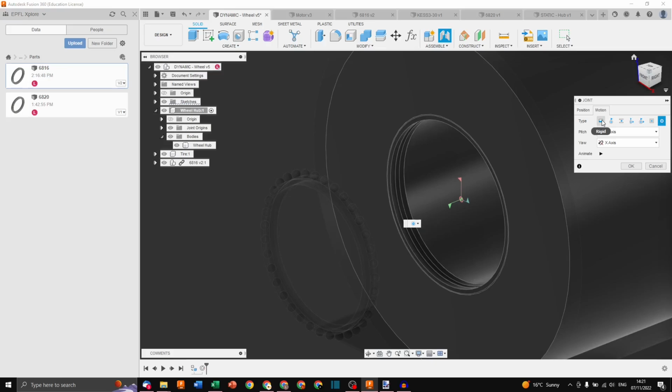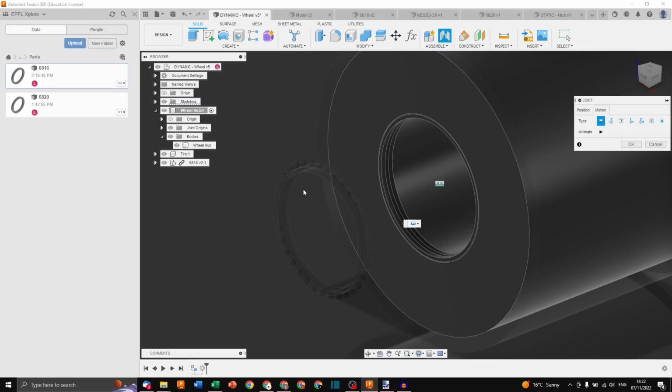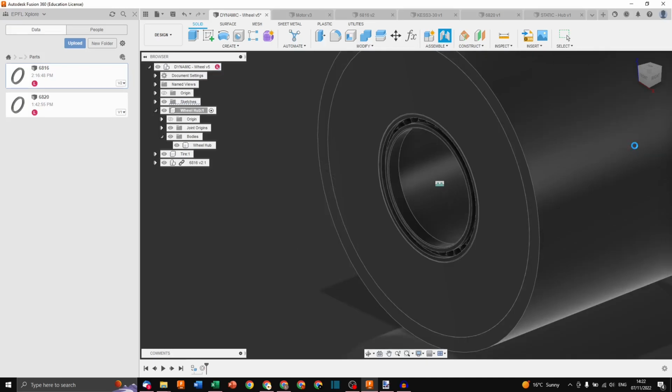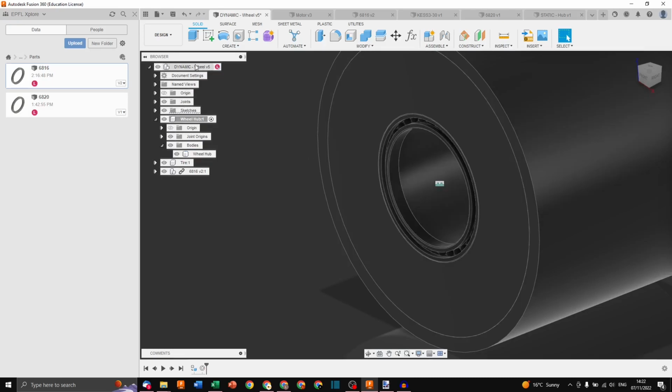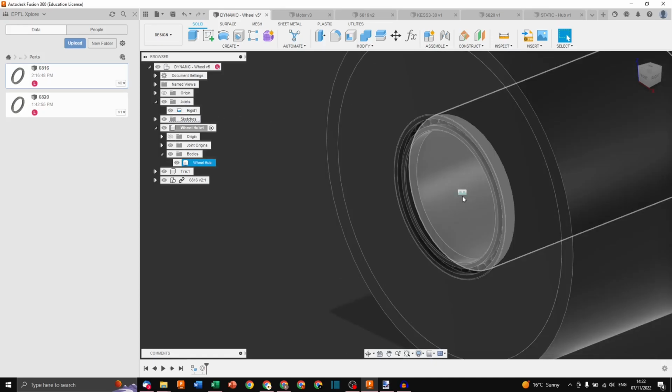So in our case, we're just leaving a rigid group. When you give the rigid group, it gives you this shaking animation to show that it's rigidly fixed. So I'll press OK, and you'll see the bearing snap back because it has to follow both rules. OK, boom. That's because the rule from the bearing and the rule from the joint are now applying. And you can see in my main menu, a new joint tab has appeared, showing this rigid joint. This diagram in space means that you've just added a rigid joint to the assembly.